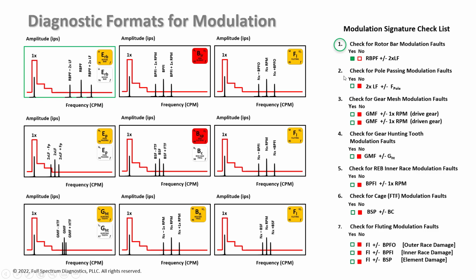Okay, and just as a note, we shouldn't go out and change the motor or do anything to it until we see changes in amplitude. It's very common to see this pulsation event going on, but the amplitudes tell us if there's actually a fault.